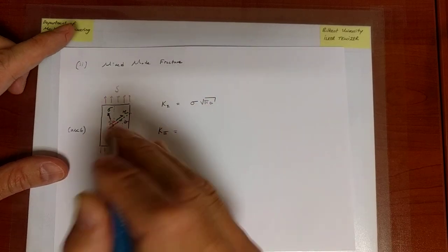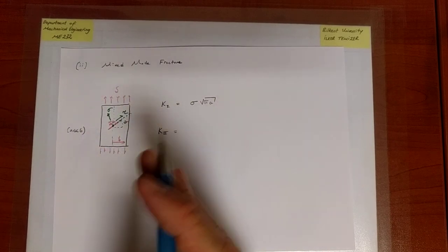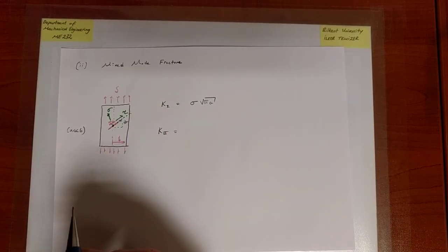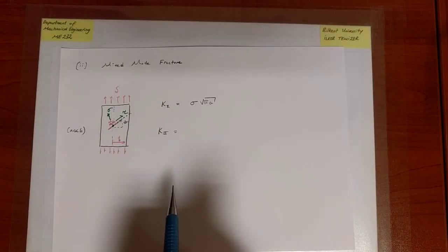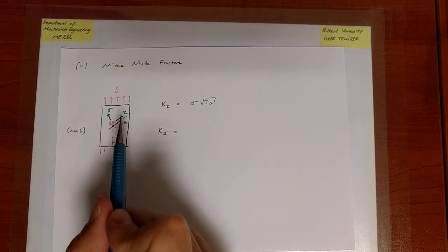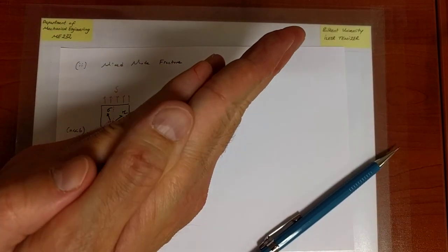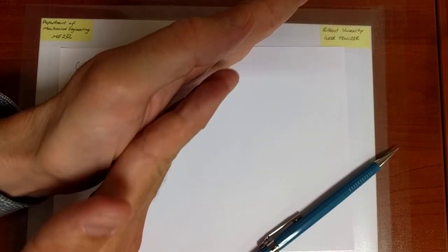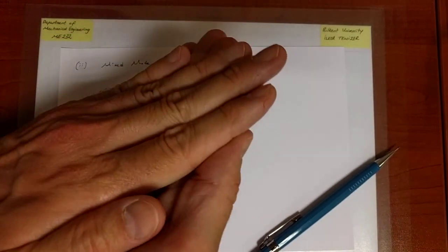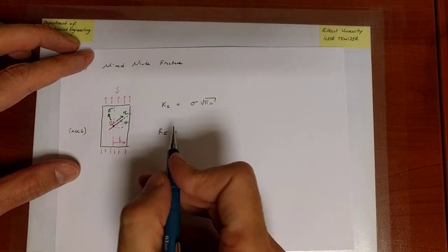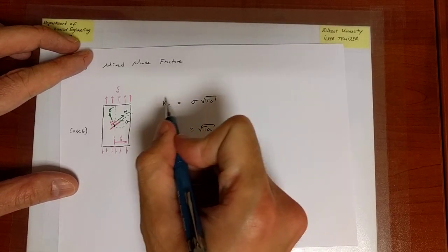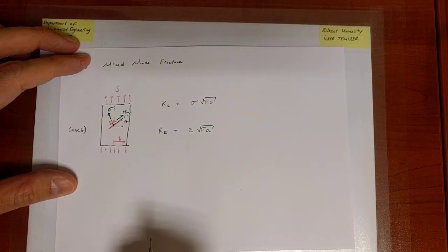Now, it's mode 2. I've said this earlier. For instance, torsion induces shear stress, and for torsion, we said that we have mode 3. That was the example that we also considered. But just like bending is not always mode 2, torsion or shear stress is not always mode 3. In fact, in this case, it's mode 2 because shear will only make the crack surfaces slide with respect to each other, just like in our initial discussion of mode 2. The surfaces do not rotate with respect to one another, they just slide. So it's actually mode 2, and therefore the way I would calculate it is like this. But notice, one of them is a normal stress, the other one has to do with a shear stress.